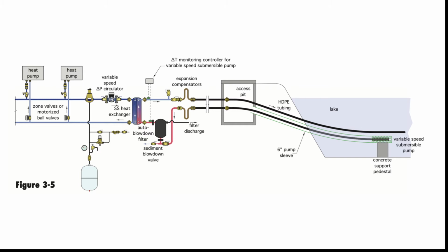When considering this type of system, it's important that there be stream flow into and out of the lake that equals the capacity of demand that the heat pump system is going to provide. Otherwise, you can anticipate turning the whole lake into a large chunk of ice, which is actually okay by design. There's a system up in Granby, Colorado that does this very same thing.